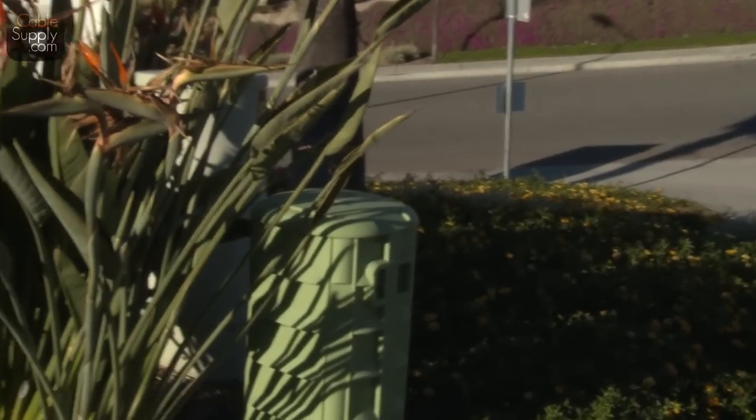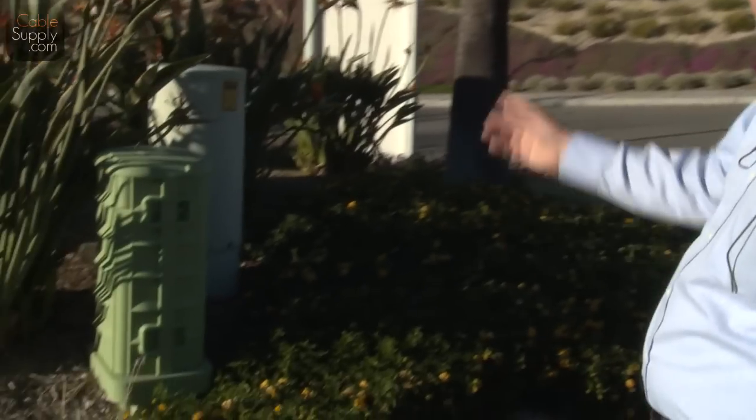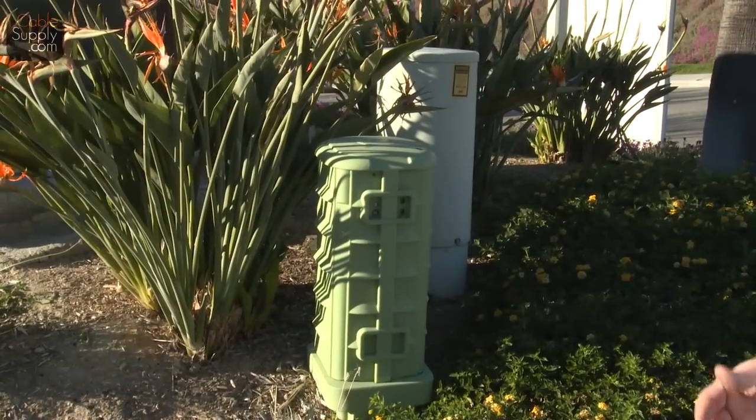But if we have a problem, what's going to happen is the telephone guy is going to come here first, and he's going to use what's called a butt set. And that's what we're going to look at next. What is a butt set? What does it do? Why you should have one. And then if he doesn't get dial tone there at the main distribution frame, or the MPO, he's going to come out here and check for dial tone here. And then if he doesn't get dial tone here, he's going to go down the street to the big frame, and he's going to check there. And if he doesn't have dial tone there, he's going to call back to his office and ask why he doesn't have dial tone. They can switch pairs, everything else. They do all that. I do not.